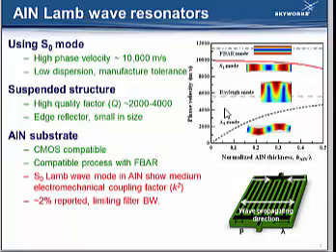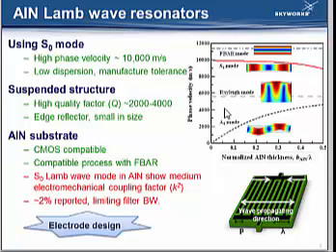However, unfortunately, the aluminum nitride Lamb wave resonator usually shows only a medium coupling coefficient. The reported results are mostly around 2%, limiting the filter bandwidth. In spite of some novel techniques to enhance the coupling coefficient, like scandium-doped or tilted aluminum nitride, actually in the first place, by just carefully designing the electrodes, the coupling can be boosted to a large extent.